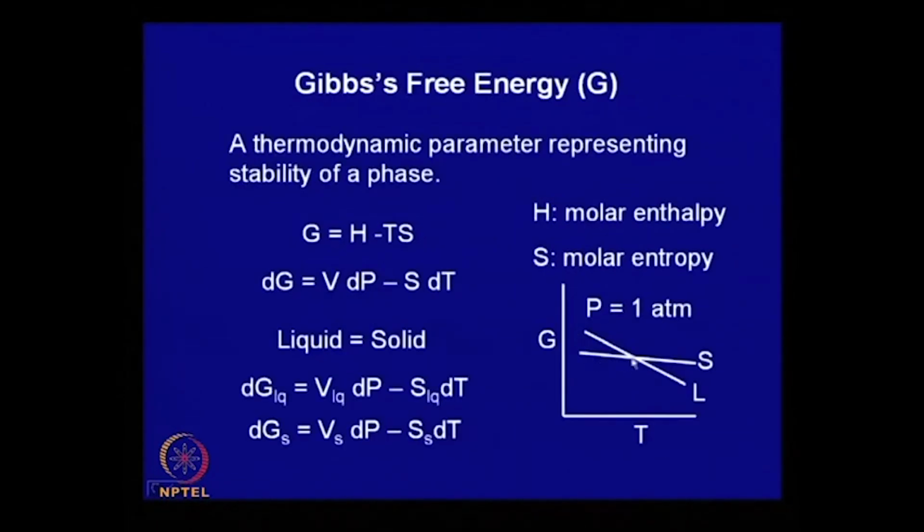so essentially what is happening is, does solidification begin immediately when it comes below the freezing point? At freezing point this is 0, but what happens when a nucleus of a solid forms? A new surface is created, and to create this surface you have to apply a certain amount of energy. Where does it come from? What is the driving force?